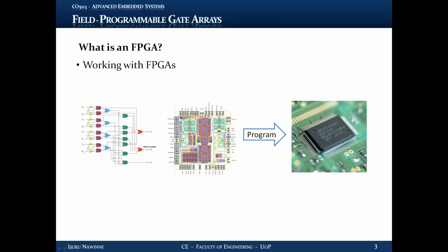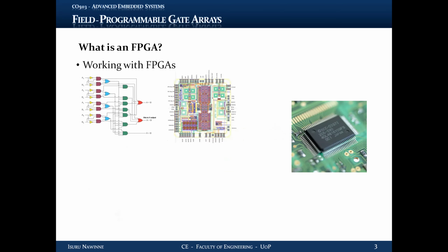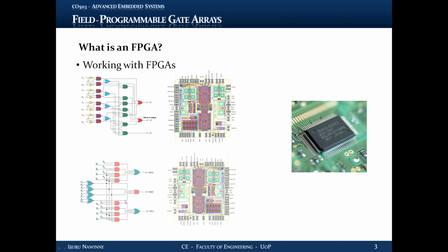So the cool thing about this is, once you have the logic circuit on the FPGA, you can get the functionality from that logic circuit. But if you want some different functionality, you can come up with a different logic circuit, synthesize it again onto the same primitives, and then put that design onto the FPGA, the very exact same FPGA, and it will host that design.